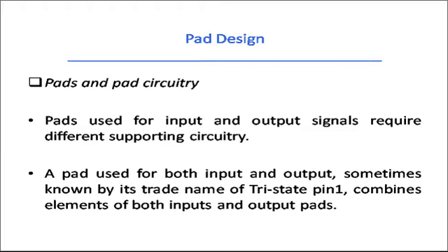Okay, a pad is used for input and output signals, and requires different supporting circuitry. For example, if you give an input, it will directly go to the inside transistor or a core logic transistor. But if you take the example of output, the output doesn't go anywhere to the internal circuitry. Rather, you may say that it is connected to a load, and the load may be a capacitive or a resistive load. A pad may be used for both input and output, and is sometimes known by its trade name, a tri-state pin, which combines the elements of both input and output. Sometimes the pad may be an input or output pad only.